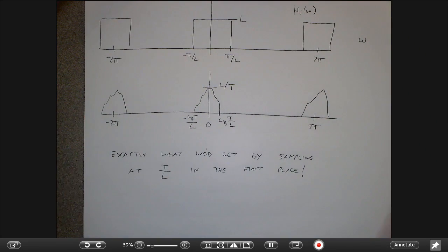So that's pretty slick. This is just saying that I can take my original samples, spread them out, put zeros in there, run that through a low-pass filter, and that low-pass filter will correctly and magically fill in the right samples in between. So that's pretty cool. That means that I don't actually have to do anything in continuous time. I just have to do the zero insertion process and the low-pass filtering in discrete time, and everything works out.